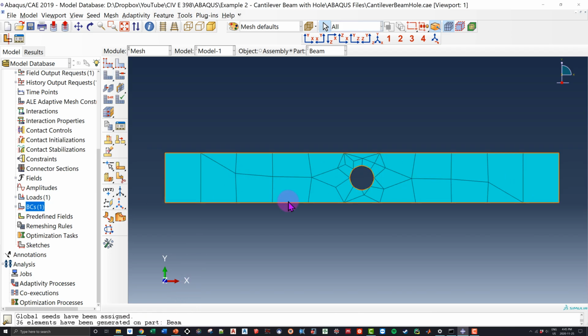What happens is we create something called nodes and elements. So if we look at this square here, this is called an element, and it's defined by 4 nodes, which are in each one of the corners. So the displacement calculations of this beam will be carried out at the nodes, and depending on those displacement calculations, the stresses and strains will be calculated inside of the element.